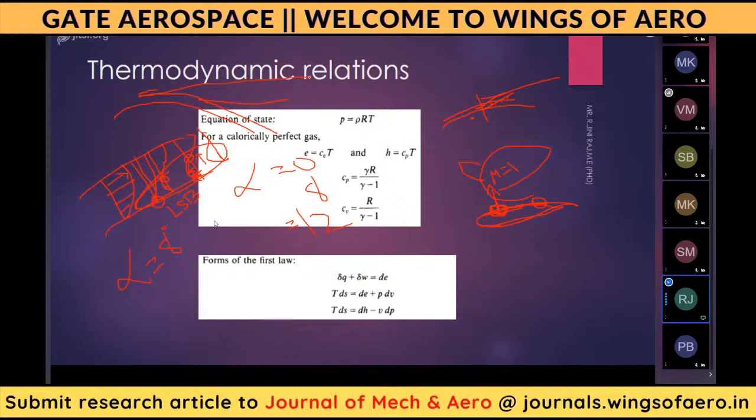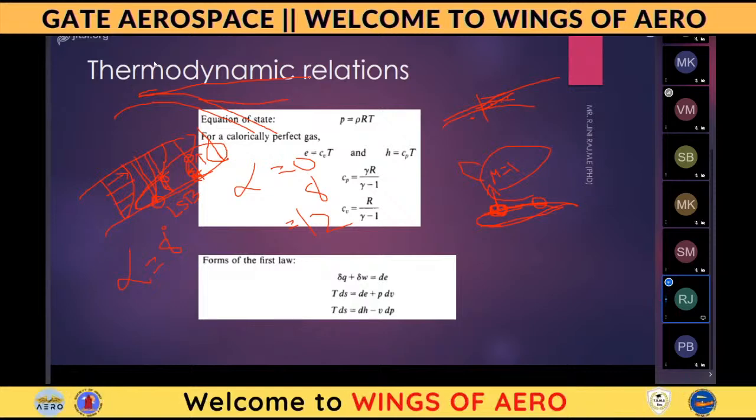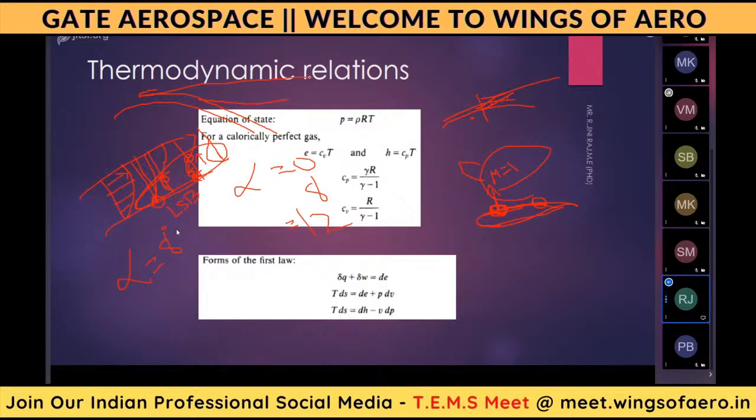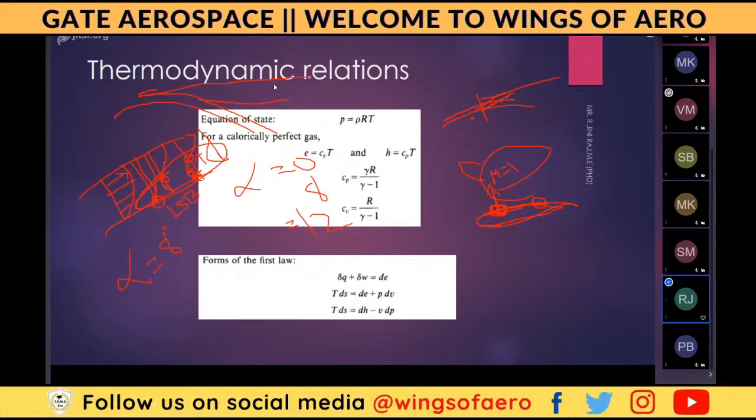So there are many concepts for designing an aerofoil, different types of aerofoils. Why are researchers focusing on this? The main thing is that at high angle of attack we will have the stalling region. After maximum CL, the wing will get stalled. So the main focus is to reduce the stall.